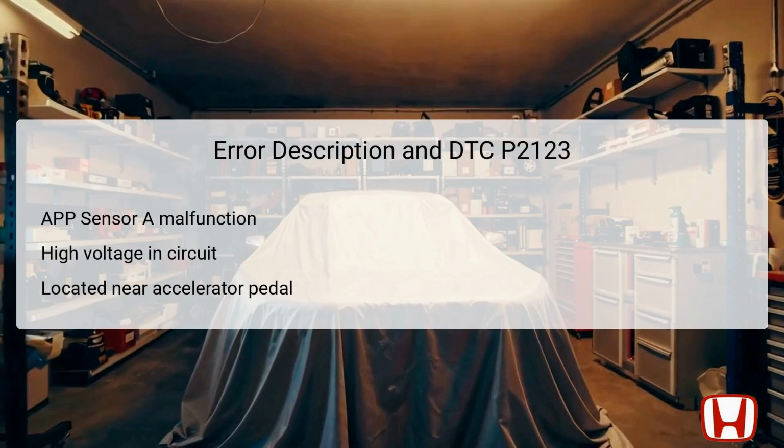DTC P2123 specifically points to a malfunction within the accelerator pedal position sensor A, commonly referred to as the APP sensor. The symptoms are identified through high voltage readings within the circuit. This APP sensor plays a critical role by ensuring the engine receives the correct throttle position information for smooth acceleration and optimal performance. Typically situated close to the accelerator pedal assembly, this sensor's position allows it to efficiently gauge how much the accelerator is pressed.